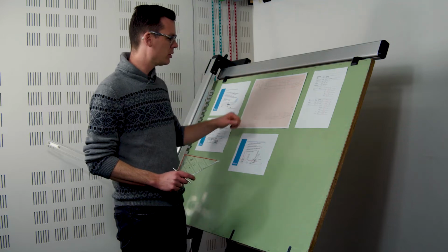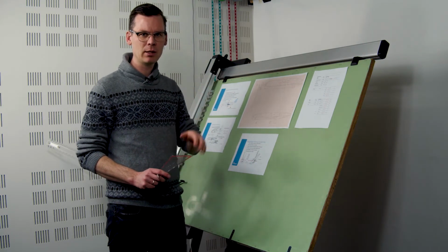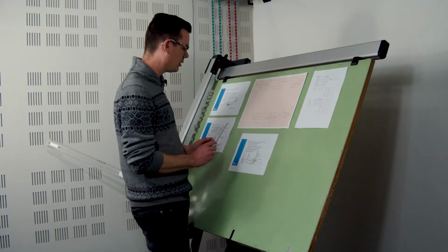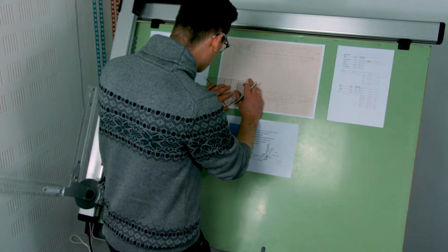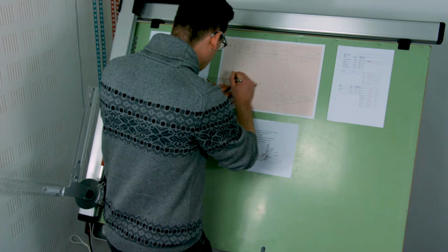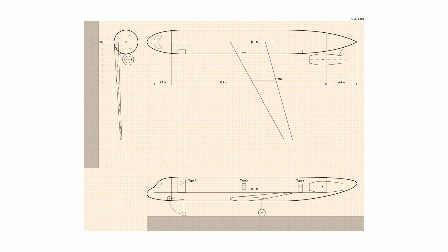So I'm using 10 degrees just to account for both the longitudinal attitude and the banked attitude change. Might seem like a lot, but we will see it's still not going to be sizing for the position of the landing gear. So 20 centimeters below the wingtip, and then an angle of about 10 degrees.